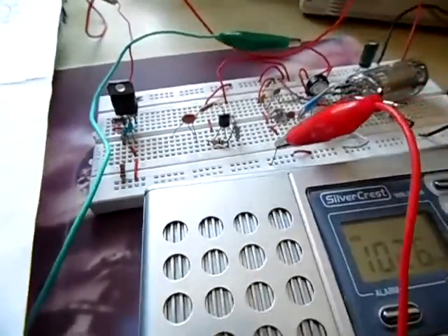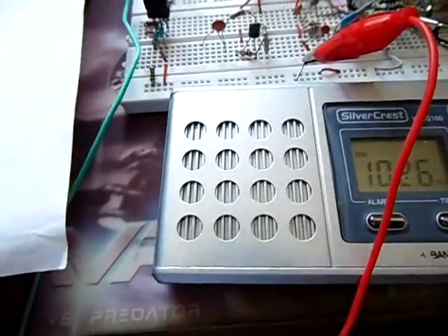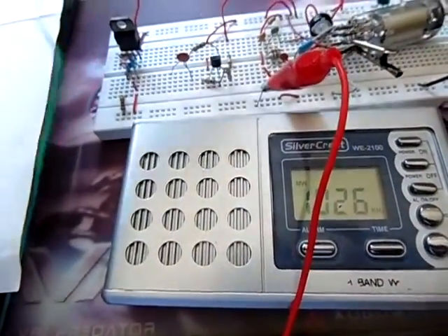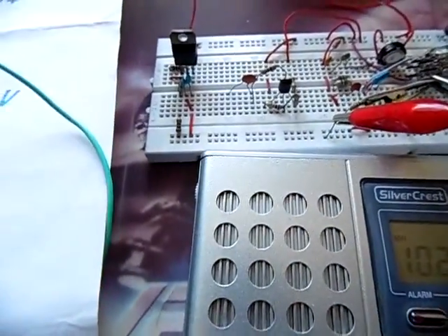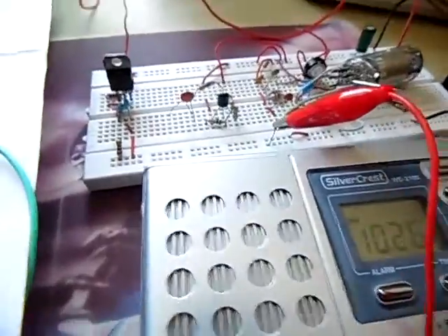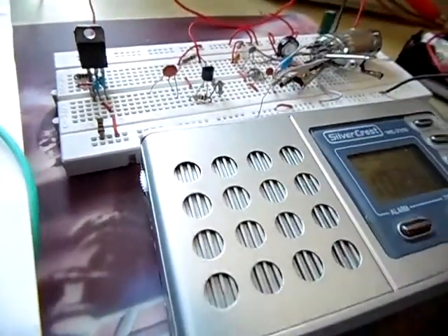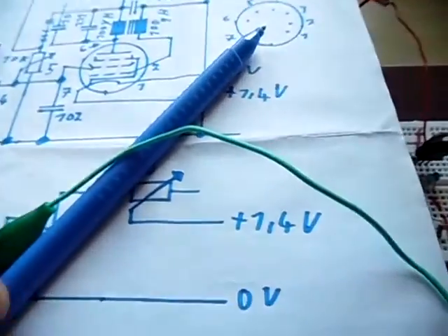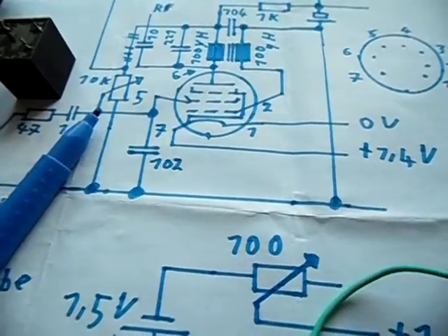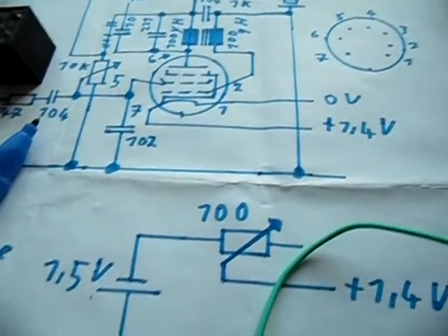It's connected. And you can hear the music from the radio, but it's very silent. Very silent. And even if I would crank up the volume to maximum on my cassette player, it would definitely get louder, but it's by far not as loud as you want to have it. And that's one problem with these tube circuits, because as they are like a field effect transistor controlled by voltage, you will require quite some high voltage on the grid to get modulation.